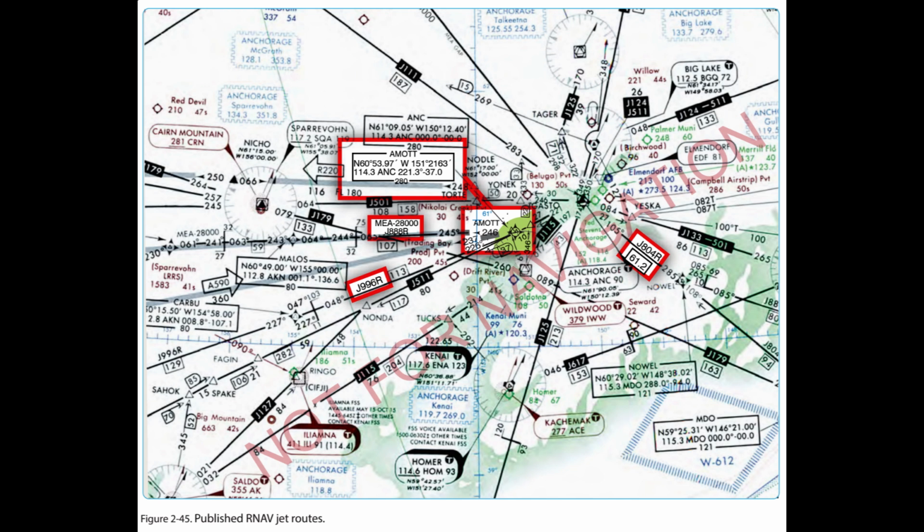4. Plan the route of flight so as to avoid prohibited and restricted airspace by 3 NM unless permission has been obtained to operate in that airspace and the appropriate ATC facility is advised.